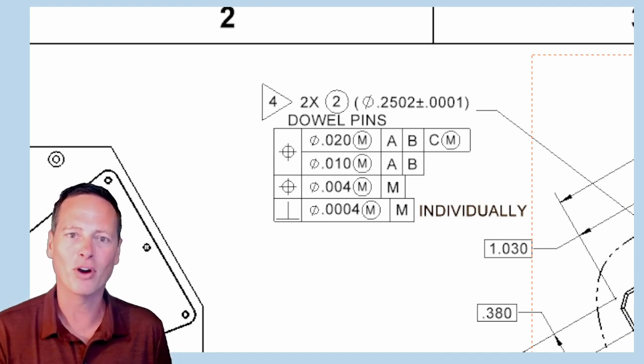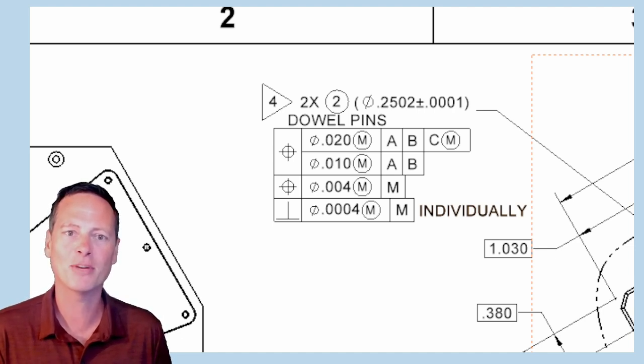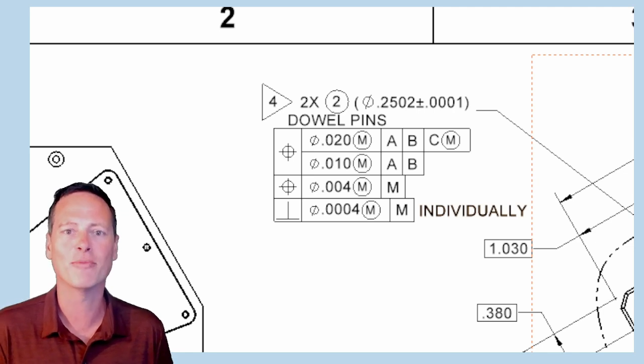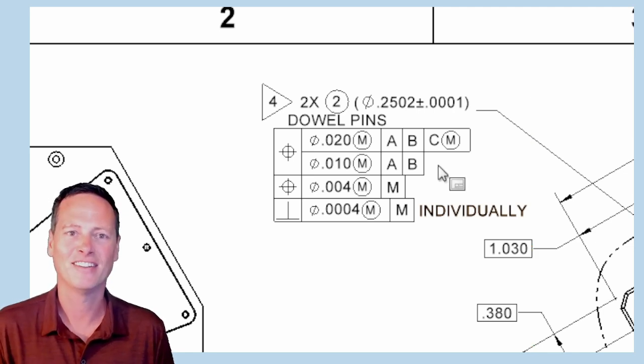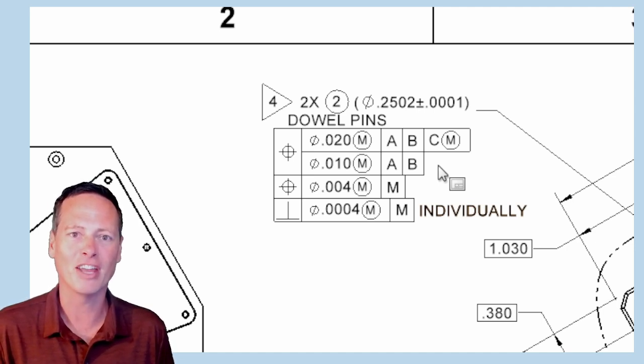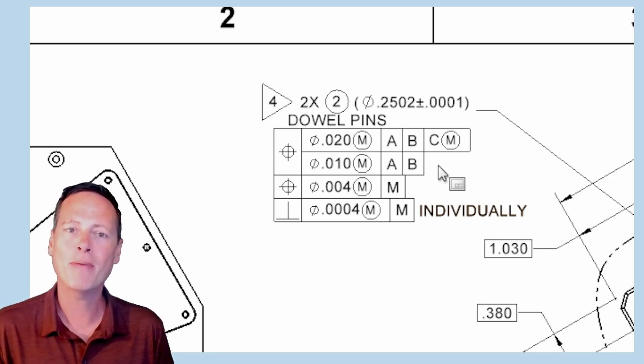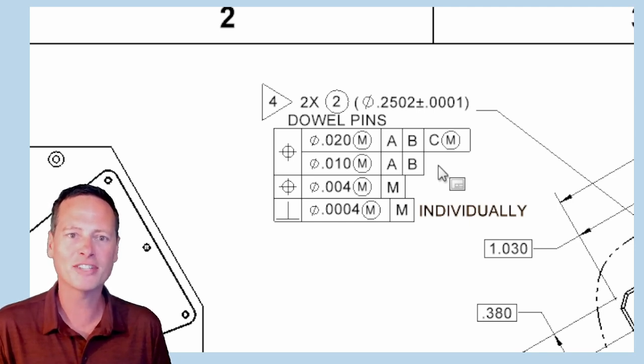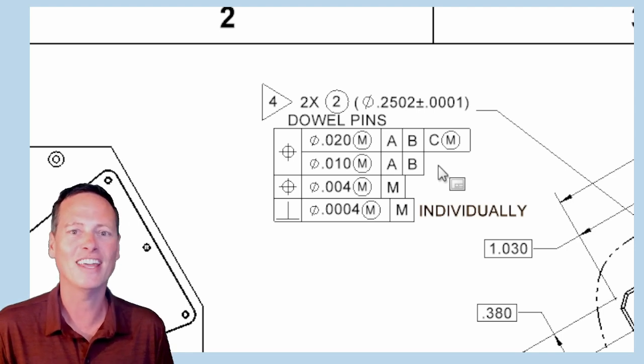Just like we had before, we still have the 20 thousandths diameter position tolerance referencing datum reference frame ABC. But how about this? Composite position with the bottom frame, the FRTZF referencing A primary, B secondary. So the pins are located to the 20 thousandths by the upper frame, the PLTZF, but then within that, the pattern is controlled in orientation to a tighter 10 thousandths in the FRTZF.